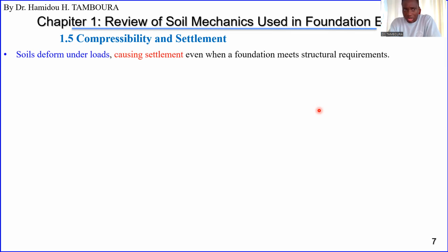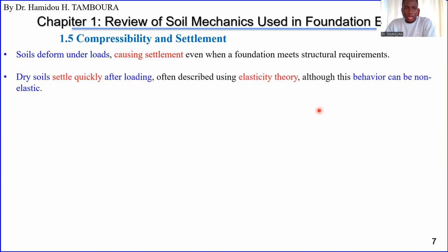So what do we know? We know that once we apply load on soil, the soil undergoes deformation, and that will cause settlement of your structure. If you are dealing with dry soil, then the settlement will happen very fast, quick.